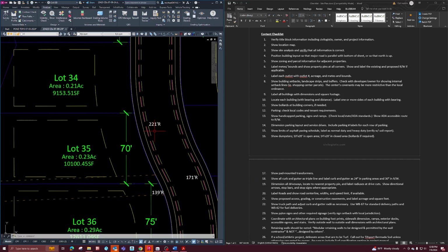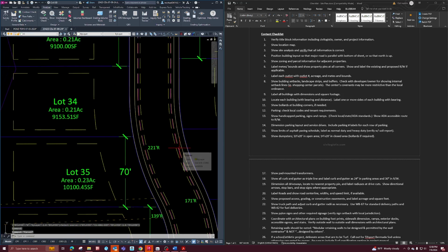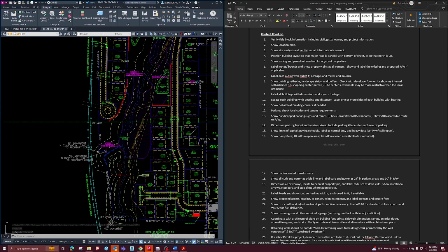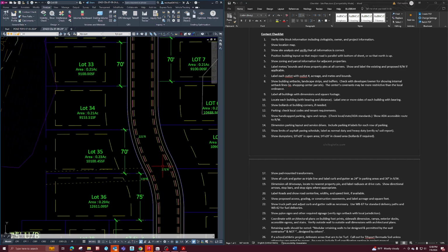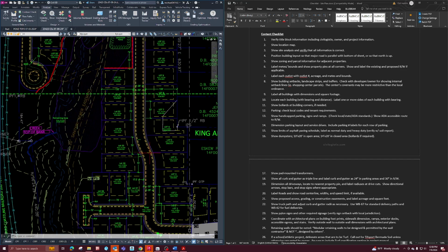That's just like our standard text height. So like if it was a 20 scale, you would do 20 times 0.08, so it'd be 1.6. But for this, it'd be 40 times 0.08, so I did 3.2. You put the dimensions on the dimension layer, and you would just keep on going along to each curve and labeling the radiuses. I'm not going to show going through and doing every one, but you just keep doing that same process along all the radii.